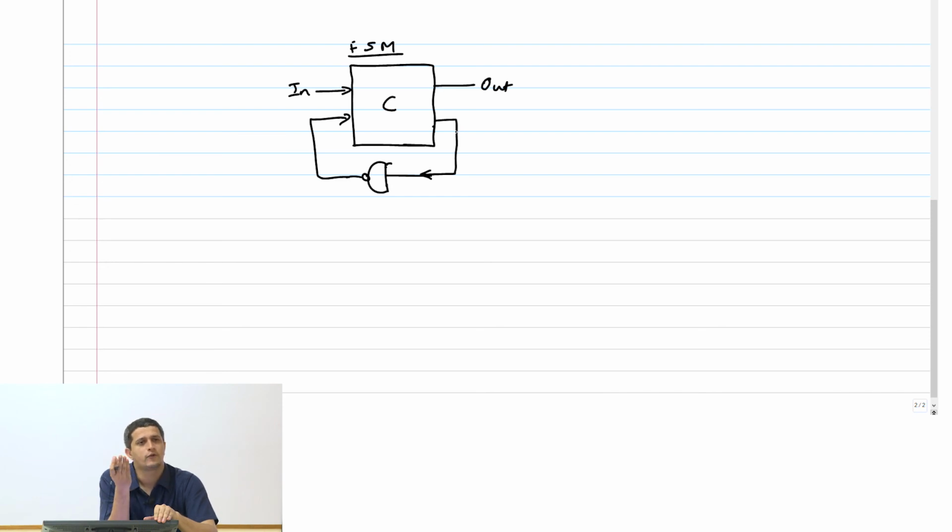So what is the need for the delay first of all? Because any change here will immediately affect this guy and that will come and override that state again, right? There is an immediate feedback there. So I need to delay that guy. If I delay it, it means that this input will be held for some time. That's what a delay means. The input will not change until that delay, even if this input changes. So if this input changes at some point, there is a delay through the gate after which this guy will change. And therefore that system can work.